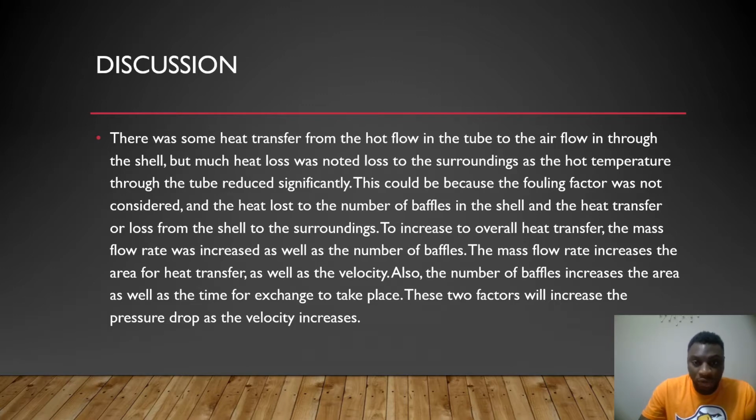This could be because of the fouling factor, which I didn't consider in this experiment, and the heat loss related to the number of baffles in the shell. Also, heat was transferred to the shell surroundings. In this experiment, I assumed I placed some coatings on the shell to reduce heat loss.